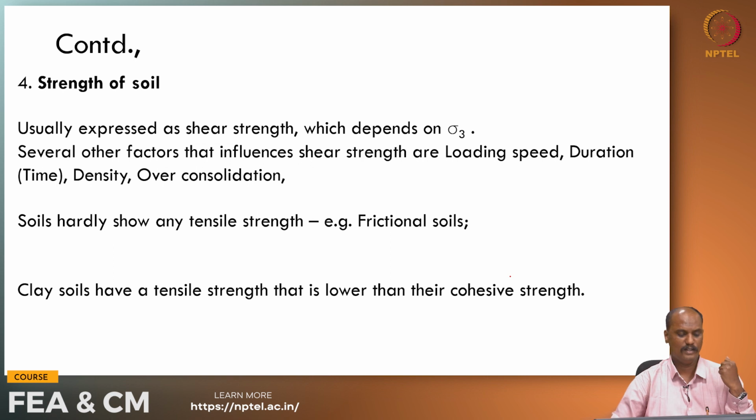And we can see that we hardly have any tensile strength with respect to soils. The tensile strength is mostly associated with clays and not with sandy soils or frictional soils. So, clays do have some tensile strength, but it is pretty much lower when compared to the cohesive strength.